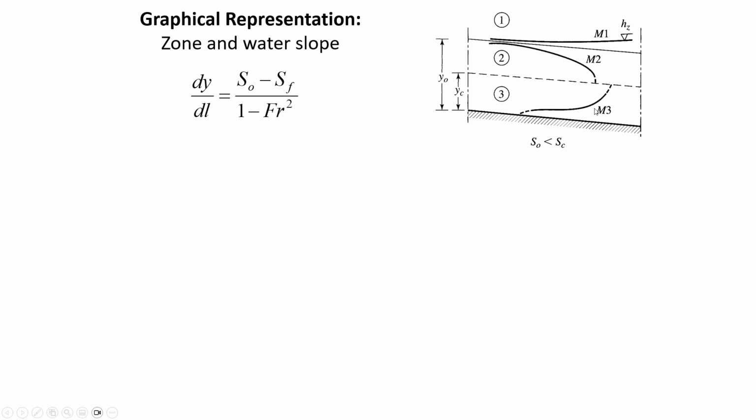So we can know a lot by comparing the water depth to the critical depth to the normal depth. So here, the normal depth is bigger than the critical. That's what makes these M's, is that we calculated both the normal and the critical, and normal was on top. So that means this is a mild slope. And then we also know, depending on where the actual observed water depth is, whether it's going to be getting deeper as you move downstream or shallower.